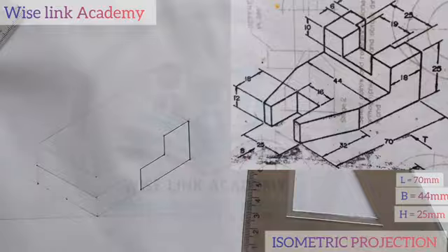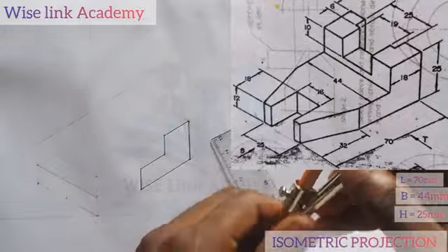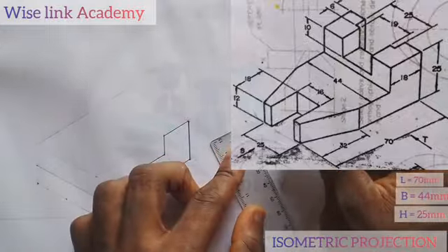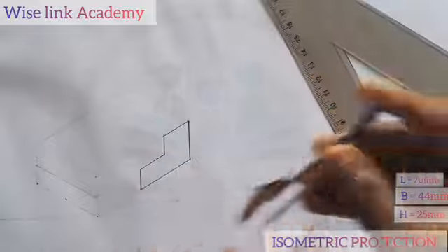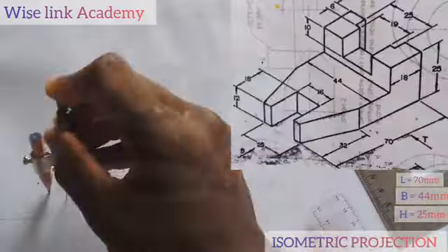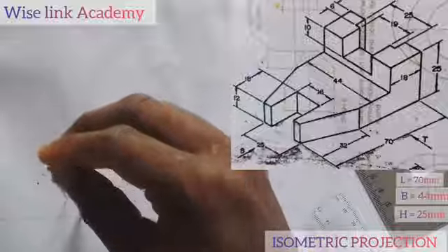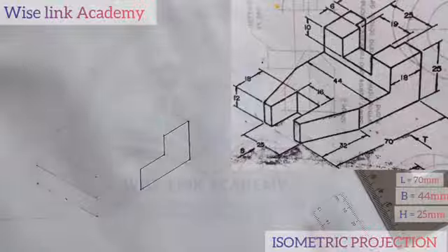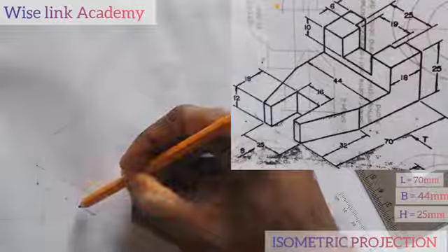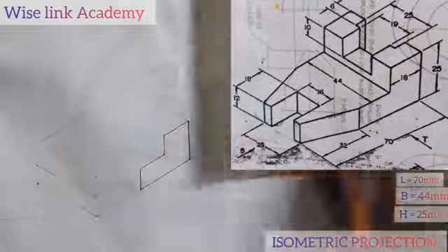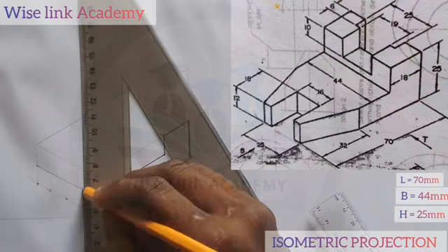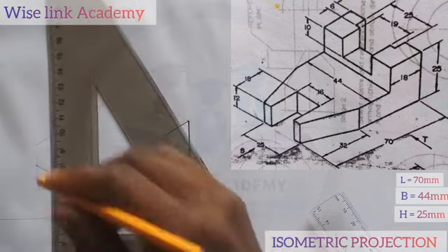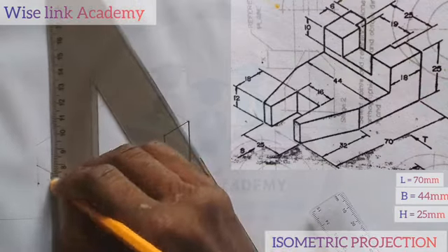That is 12.5. So then with my compass, I will measure 12.5, that is 1.2 at this point to this point. I'll place it at this point here. Strike an arc 1 and another arc 2. So at that arc, this place and this place, I will take with the help of my set square this way, I will take this upward to touch this. Also, at this point, I'll take it upward to touch this.